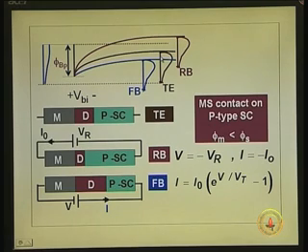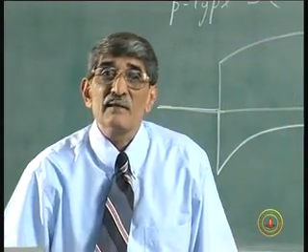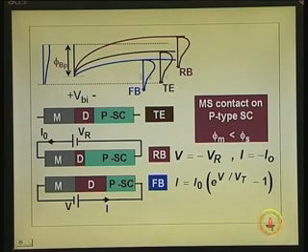Okay. Now, the polarity of this built in potential is plus here, minus here, because phi m was less than phi s, the Fermi level in the metal was at a higher level, and the difference is less compared to that. So, electrons have got transferred from the metal to the semiconductor, and you have a plus minus voltage there, a built in potential exactly opposite to that of the metal n layer. So, reverse. So, this is the V BI.